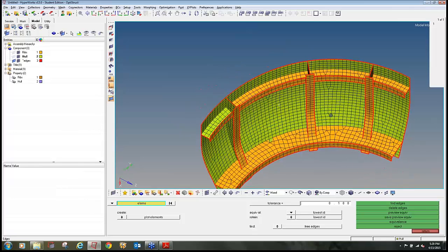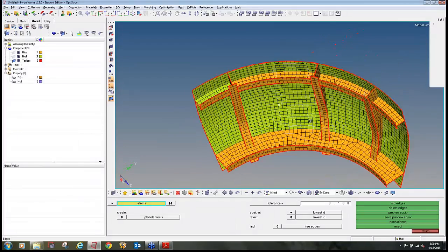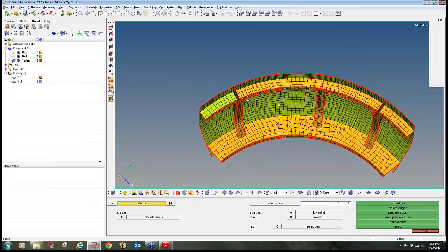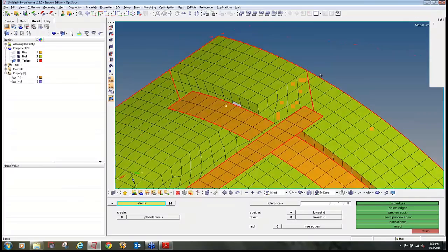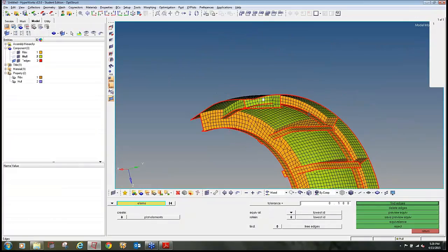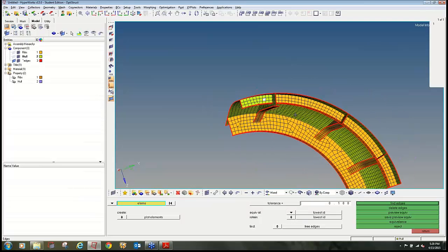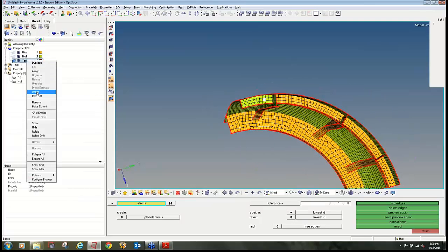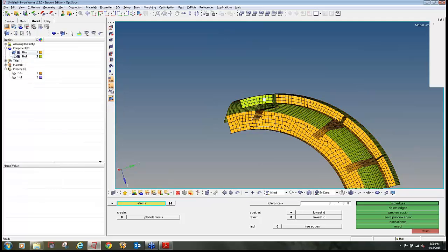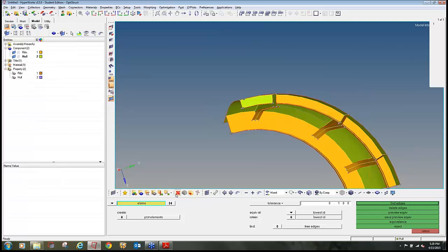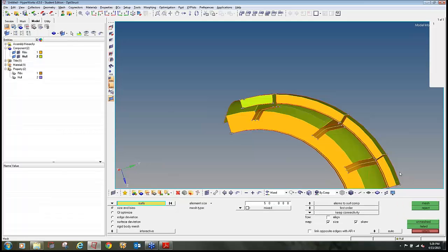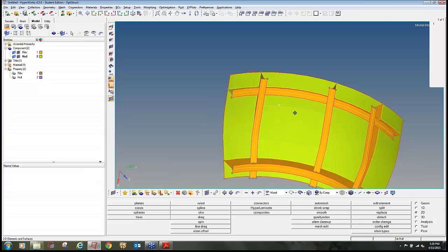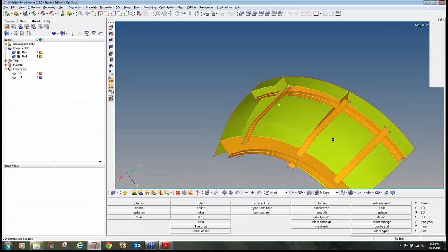Okay, something is wrong in this area. This area has got the element properties of the other areas also. So I will delete this component on the surfaces and delete the elements. While editing, the surface moved to a different component.